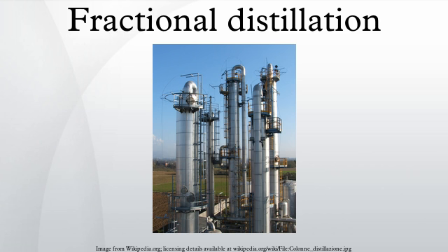Large-scale industrial towers use reflux to achieve a more complete separation of products. Reflux refers to the portion of the condensed overhead liquid product from a distillation or fractionation tower that is returned to the upper part of the tower, as shown in the schematic diagram of a typical, large-scale industrial distillation tower. Inside the tower, the reflux liquid flowing downwards provides the cooling needed to condense the vapors flowing upwards, thereby increasing the effectiveness of the distillation tower.